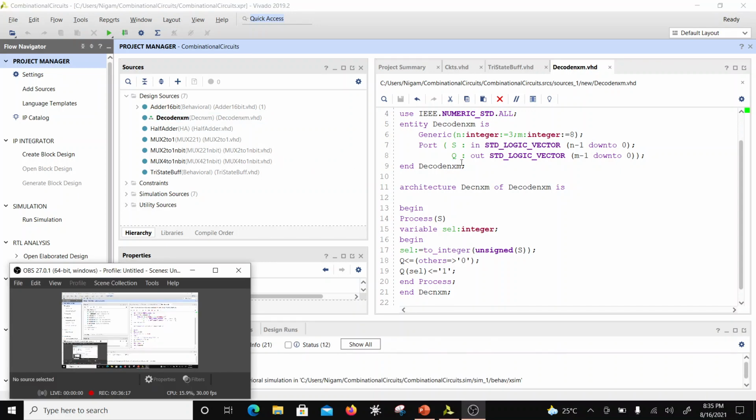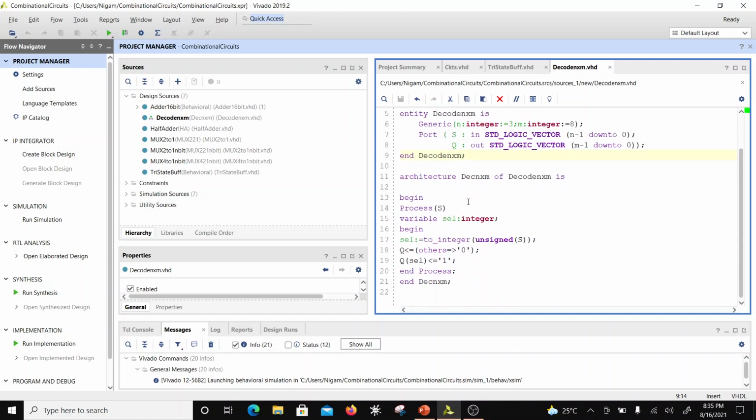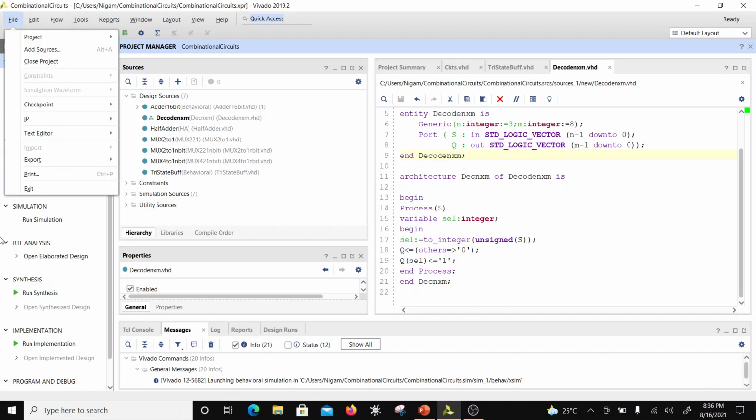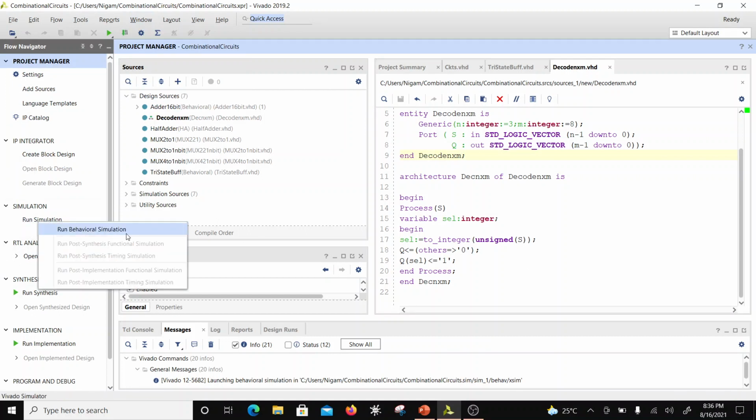Okay, the spawn error occurs when there is a compilation issue. When the sequencing of the files which are compiled and not compiled is affected, then it gives a spawn error. So all you have to do is nothing but just repeat the run again. So I am going to save everything and run the simulation again.